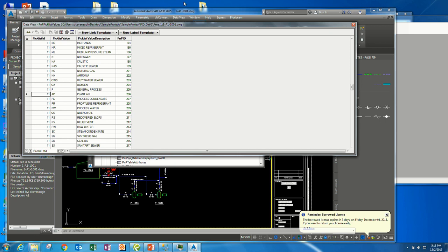So what you'll do is you'll create a new project, but you'll create a SQLite project. If you don't want it on a database, or if you want to make it mobile, you can create a SQLite project, copy all those drawings into that new project, and then you have a packaged project that's accessible, mobile. And then if you want to bring it to a new home, put it into the computer, run the conversion, convert it, and then put it on a SQL. Exactly. So that's how you package that up.